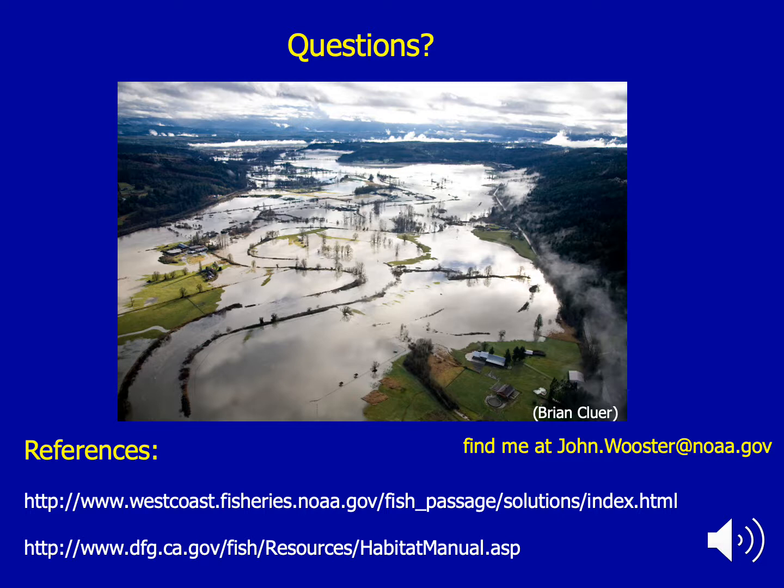You can see that naturally these have high floodplain connectivity. Trying to establish a stream crossing in systems like this is very challenging. Often in this type of system, we like to grab one channel and try to make it the dominant one. Down here in a meandering system, at the time of establishing a crossing, often there is a clear-cut single-thread system, but when you do that, many times you isolate yourself from accessing a lot of these remnant channels here.